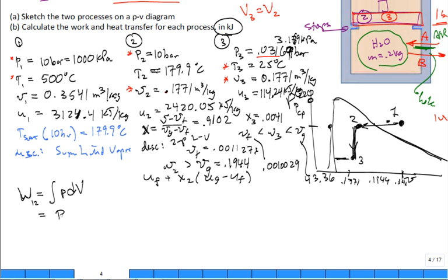So we find the pressure times the mass times the final specific volume minus the initial specific volume. Done those a few times. What is the pressure? Put in 1,000 kilopascal, because that's my favorite pressure when I'm multiplying by meters cubed per kilogram on the specific volume.